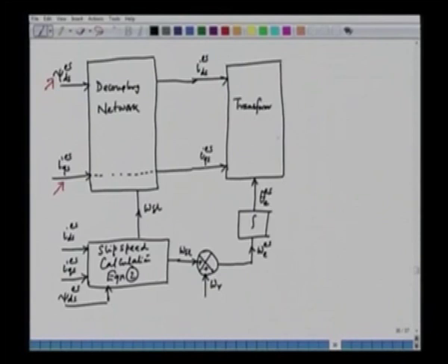And then after this transformation from IDS to IQS using theta E, what we obtain here is the reference 3-phase current IA, IB, IC. They are the reference current. So, we can denote them as IA star, IB star, and IC star. And the reference currents that we have can be impressed on the machine using an inverter.